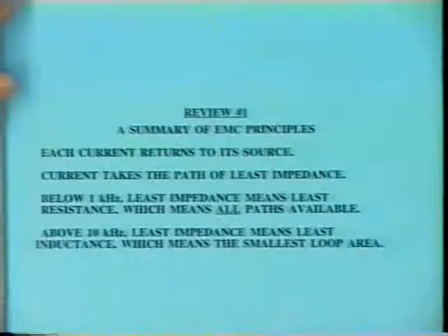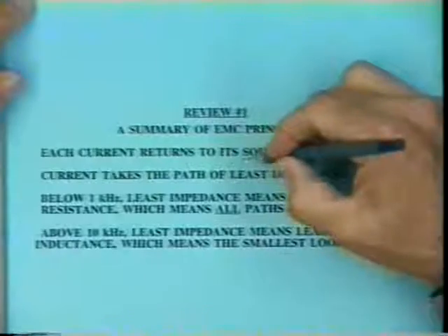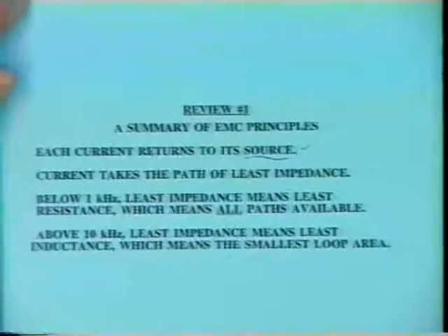Every current, we said, eventually returns back to its source. It seems like a simple principle, and it is, but once in a while we forget this. We think currents go to ground, but currents always return back to their source. This is true of signal currents, noise currents, and, of course, power currents.